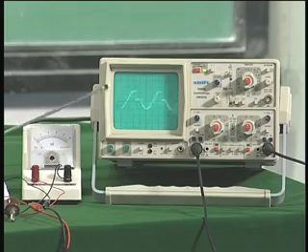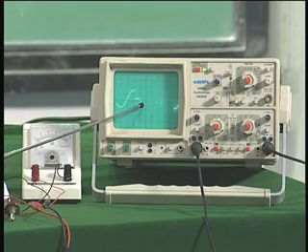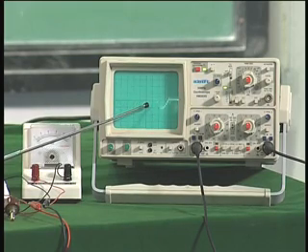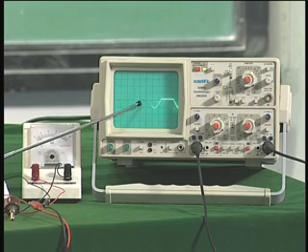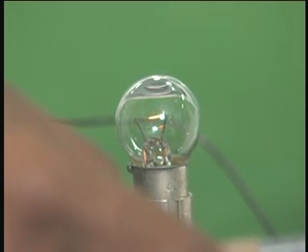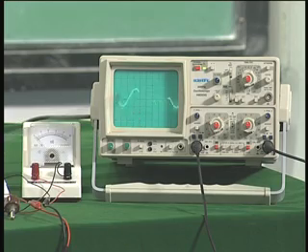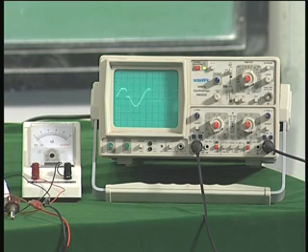So, the energy supplied to the load is changed by changing the angle of conduction, and that is what is clearly seen here. Now, it is almost full bright, and then if I reduce it, you can see the variation can be changed corresponding to the waveform that you see here, right. So, this is corresponding to the AC control of the SCR.